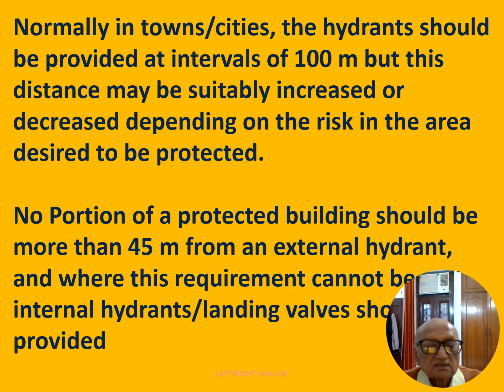Friends, so far we have discussed the yard hydrant system for a particular campus. But normally in towns or cities, the hydrant should be provided at interval of 100 meter, and this distance may be suitably increased or decreased depending upon the risk in the area desired to be protected.